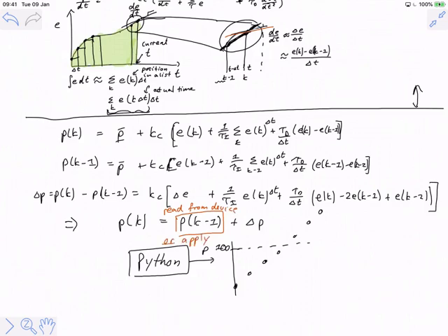Or if I apply limits on the controller output within my program and remember the limited value. If I don't do one of those two things, my controllers in velocity form and position form are exactly the same, because the math works out, as you can see, exactly the same.